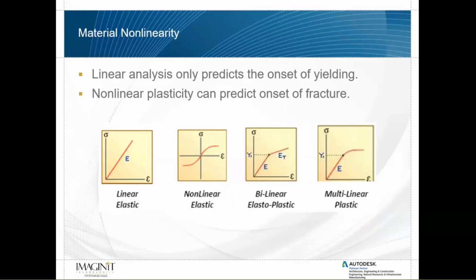This is a pretty good way to look at materials when you're first getting into nonlinear static analysis. It is an approximation, so it's not going to be perfect, but it does give you a good representation of which elements go plastic, and it'll give you an approximation of the amount of displacement that occurs due to that deformation. This is also a great way to look at aluminum materials, because typically aluminum materials will have a nonlinear working range that's fairly flat. So its nonlinear static curve will be close to your tangent modulus approximation.